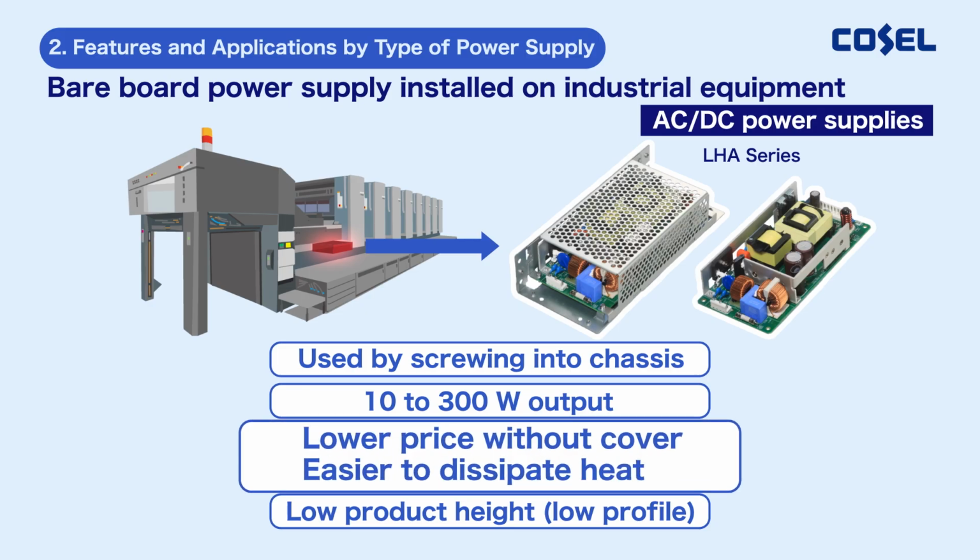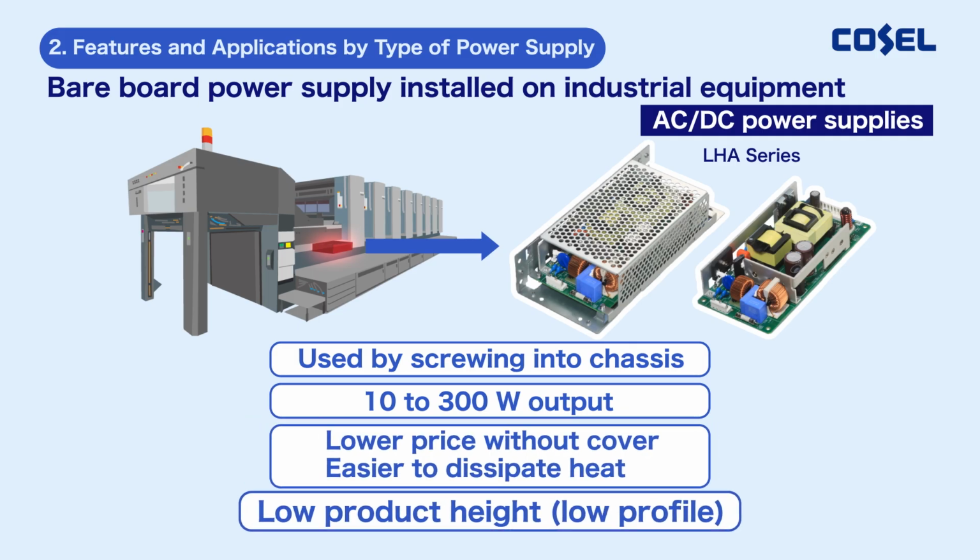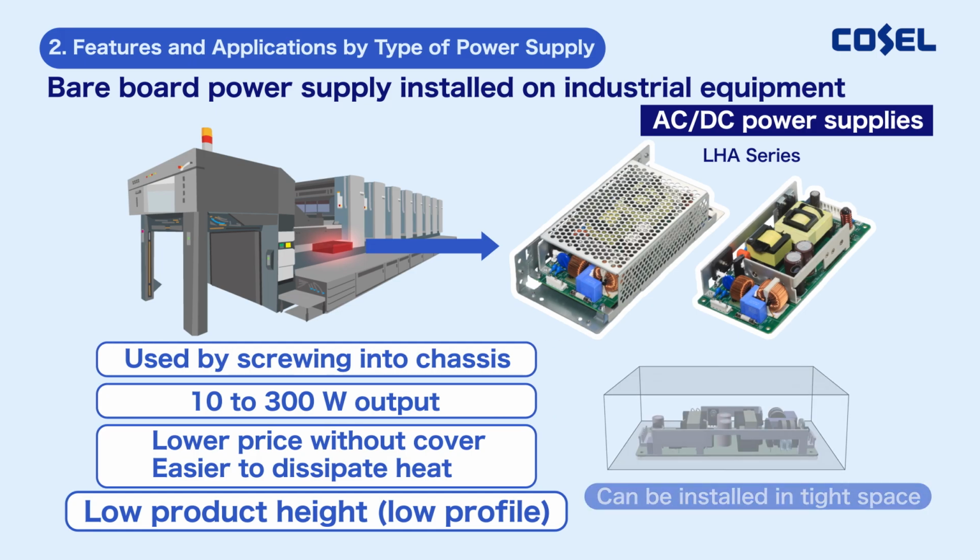The advantages of not having a cover are lower cost, better heat dissipation, ambient temperature derating, and longer power supply lifespan. Additionally, due to the low height of the product, it is often used side by side with other control boards and the like during user mounting.